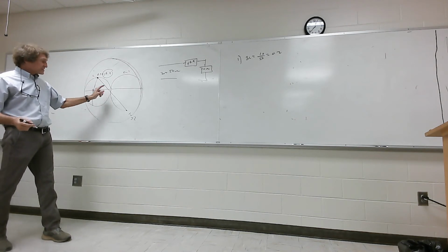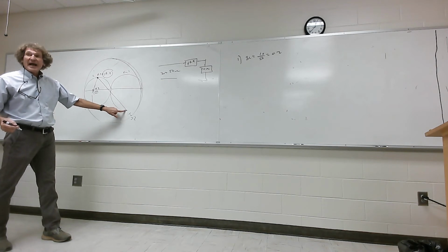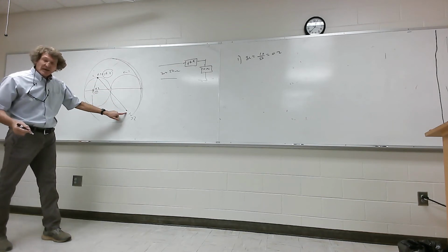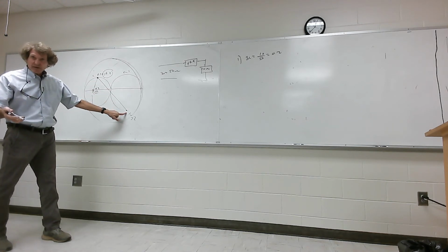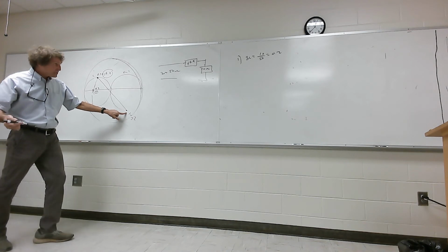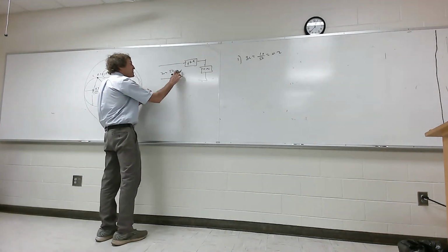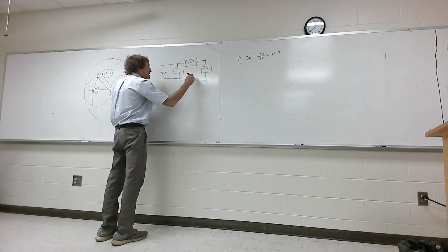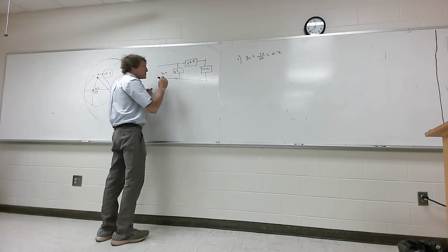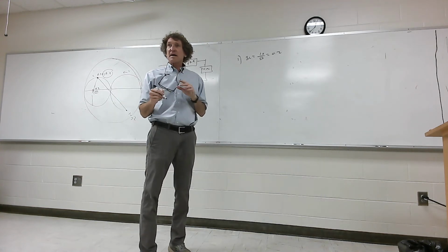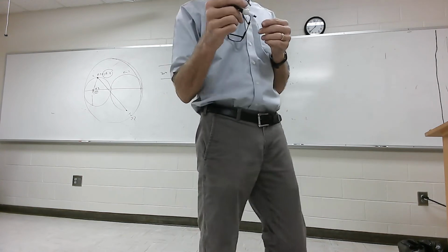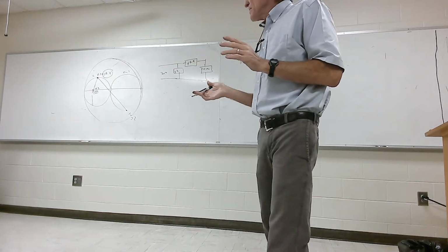And that would be what? That was impedance. This would be a capacitor in parallel, correct, class? We were at impedance, we add an inductor, we come to this domain, we're admittance, it's in parallel. Now we're going to add a capacitor that has a value of plus J2. So here, a capacitor of J2. That's admittance. Now we're going to get the values. But does everybody follow the thought process? The whole idea is just adding things, so eventually you get to the center.